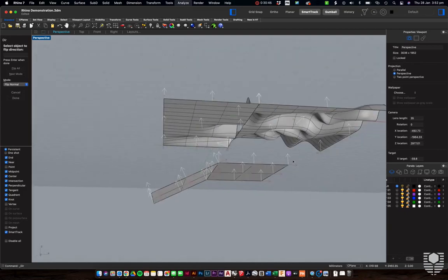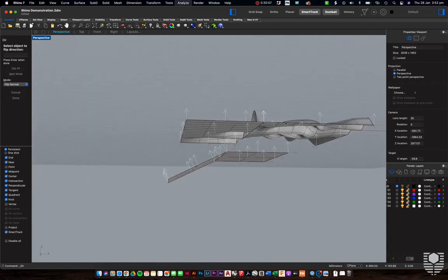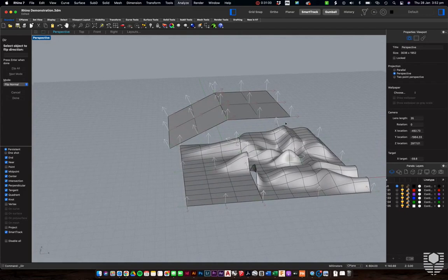But effectively what it means is that upwards away from where we are right now is the top, and the underside here is the bottom. Now, what's going on at the moment is correct. If, however, we have something like this, where one surface is up here and another surface is down here, we're going to be telling the 3D printer some confusing messages that this is the inside here and this is the outside here, and it ends up being a problem. So we do need to always check that our surface is correct, and that was just through Analyze and Direction. And you can also change the normals just by clicking anywhere on the surface. That will change the direction of the normals for you there. Once you're done, hit enter to finish.